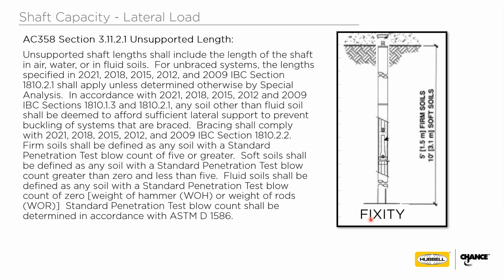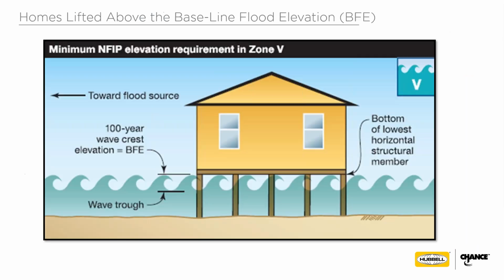But we also have to look at scour as part of that, as you saw in several of those pictures that Kerry showed you, that scour is a significant event when it comes to the storm surge and flood. So we often have to, depending on locations, look at scour in addition to this when we look at the overall pile length for a given location.